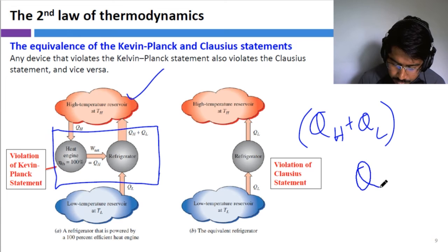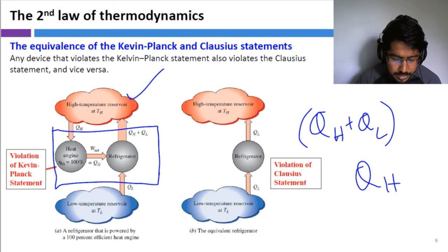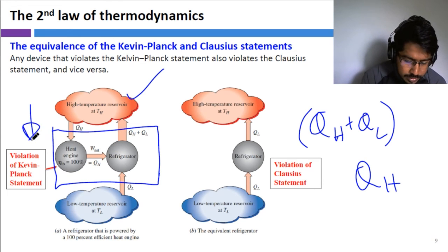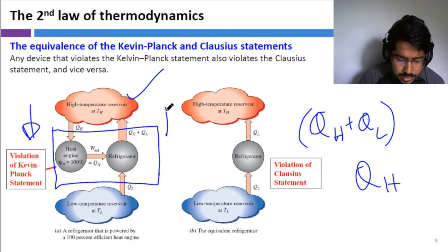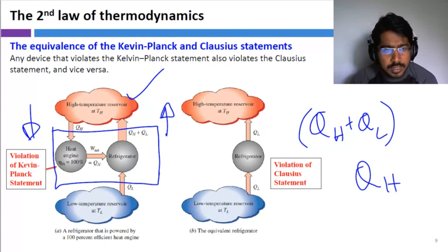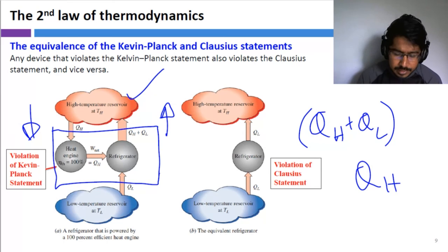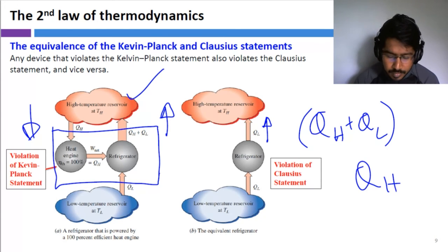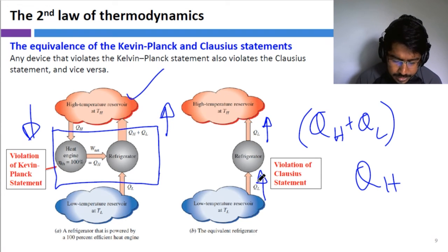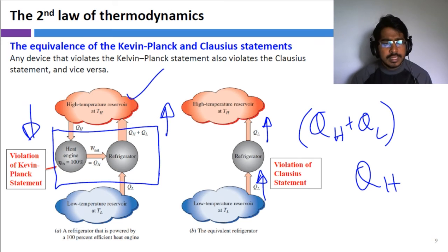and there's a QH going in the opposite direction, right? QH received at the device and QH plus QL was ejected by the device. So the net effect is going to be QL ejected by the device. And then again, QL here does not change. It was the amount of energy that we absorb from a low temperature reservoir, right?